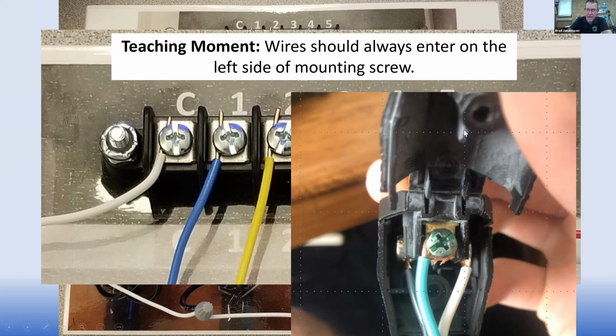Okay. But in a control setting like this, where you're not going to have a lot of pulling going on, I wouldn't do it. You could, but you wouldn't necessarily have to. If it's an extension cord plug or a wiring plug or a connector, absolutely. Anything that you can do to help solidify this, or if you're working with house wiring, I always try to twist them around there. But within a controller like this, normally you don't necessarily have to, but it doesn't hurt.